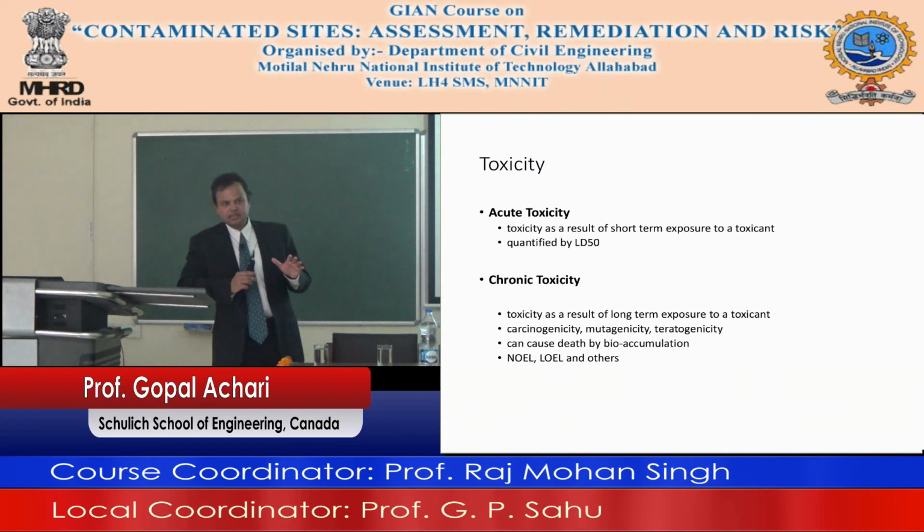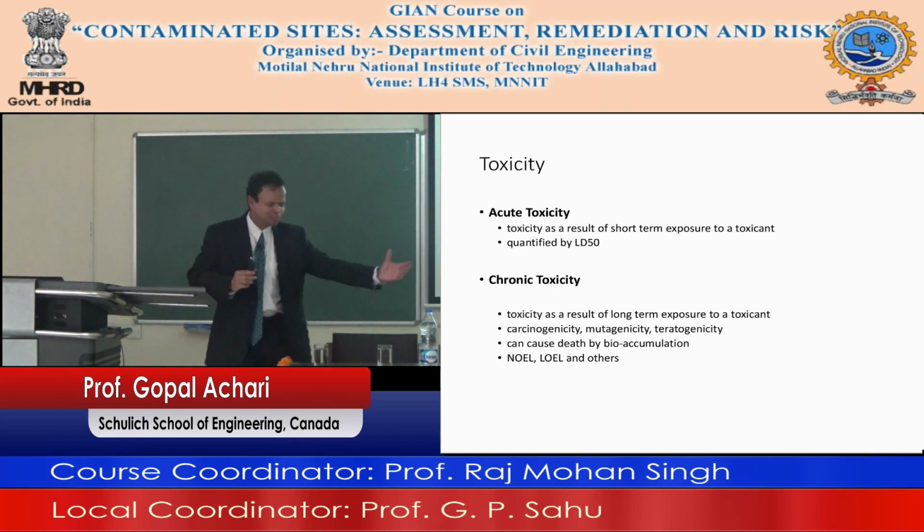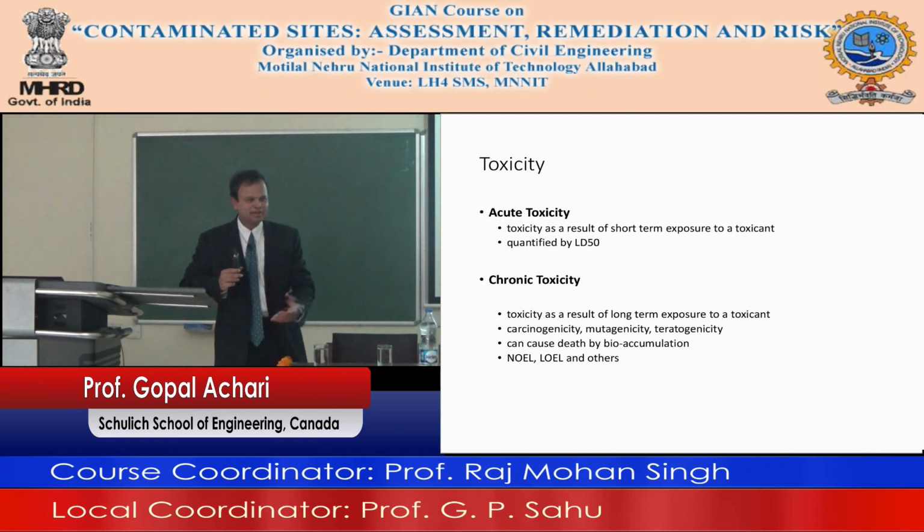You know what LD50 is? Finish that sentence. No, lethal dose that kills 50% of the fish or whatever is your target, right? So that's the lethal dose that kills 50% of the fish. That's LD50, right? But think about us as environmental engineers. What does that mean? If I take a bowl of water, right? And I put some experiment, I find that at this dose, 50% of the fish are killed. What are you going to tell people?